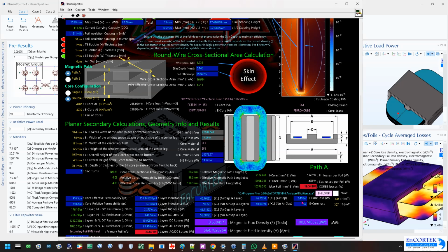So when you punch in this here and have this over here, you'll be doing these other calculations. And over here now we could change the scaling, because some data sheets give you millihenry, some give you nanohenry, right? So whatever it is you're choosing, you're putting in for the I core, the E core itself, how many cores you want. This core is just one core, right? So if you want to have a pair and make it longer for a high voltage transformer, it's pretty much going to be multiple cores.